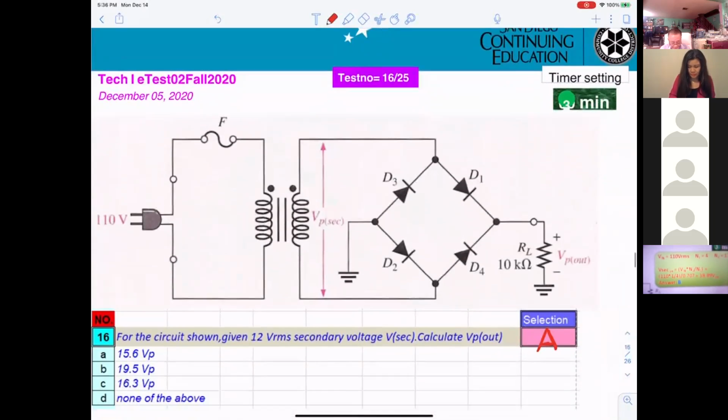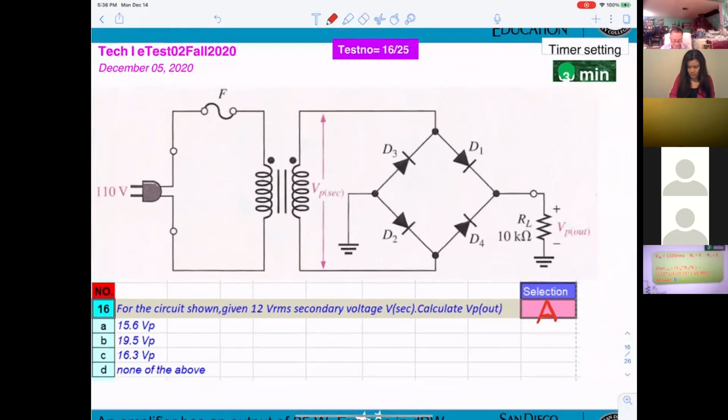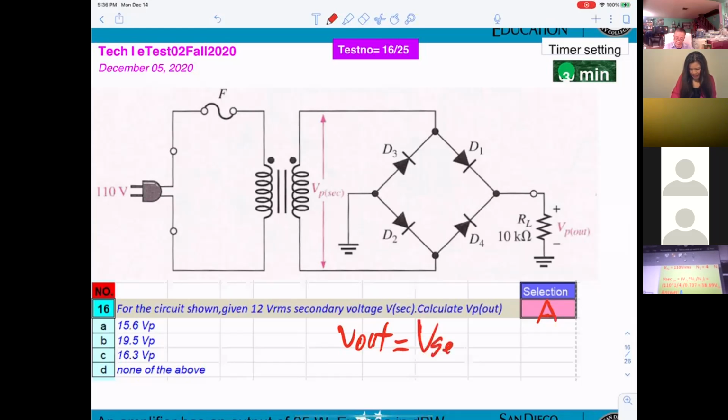V peak. I think she wants you to write it down so she can copy it and study it. So I'm already telling you, V out, 17 divided by 1.4. No, not divide. Oh, subtract. Subtract, thank you. It's the two voltage drops across the two conducting diodes.